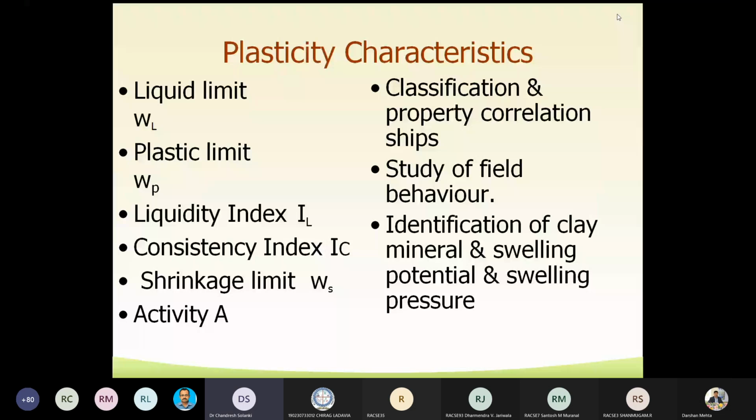Many of you may know how to classify the soil in detail, as far as coarse-grained soil classification and fine-grained soil classification are concerned. Soil indices are very, very important to know the degree of firmness of the fine-grained soils. Shrinkage limit is important in knowing the expansiveness of the soil. Activity number is also important in knowing the expansiveness of the soil. So all these things are required.